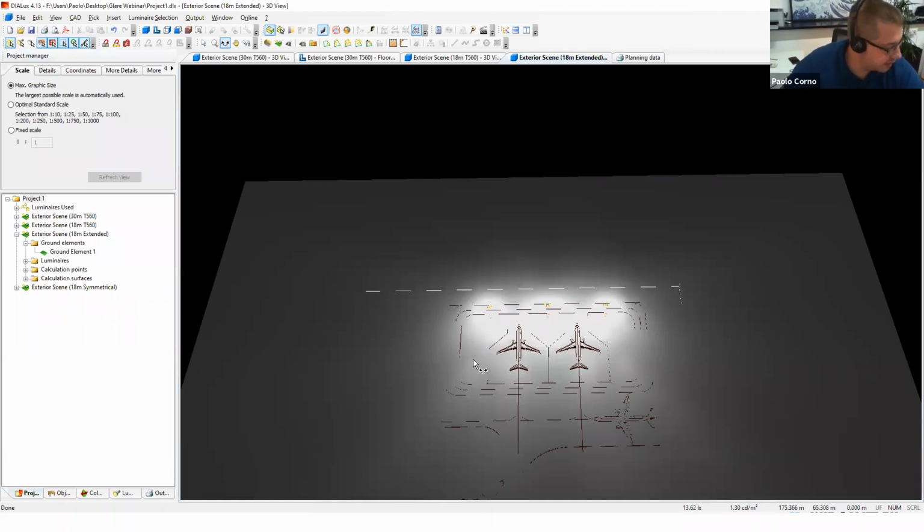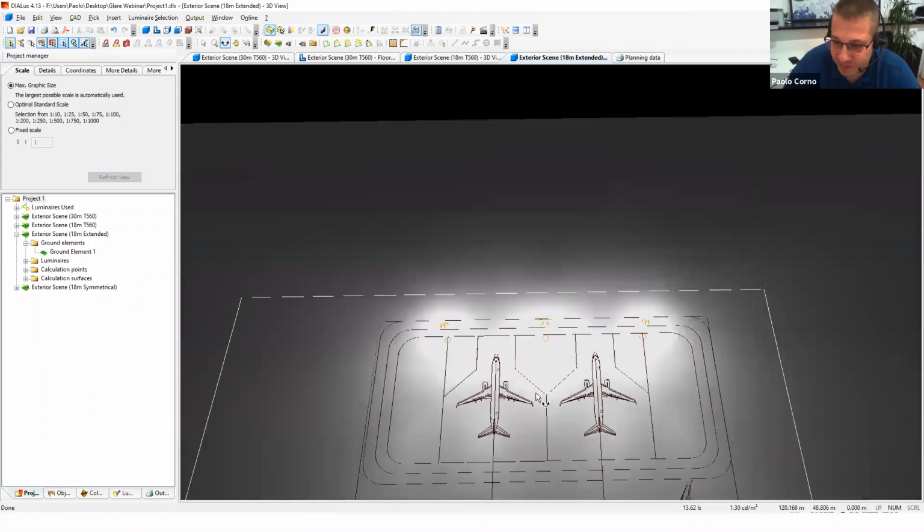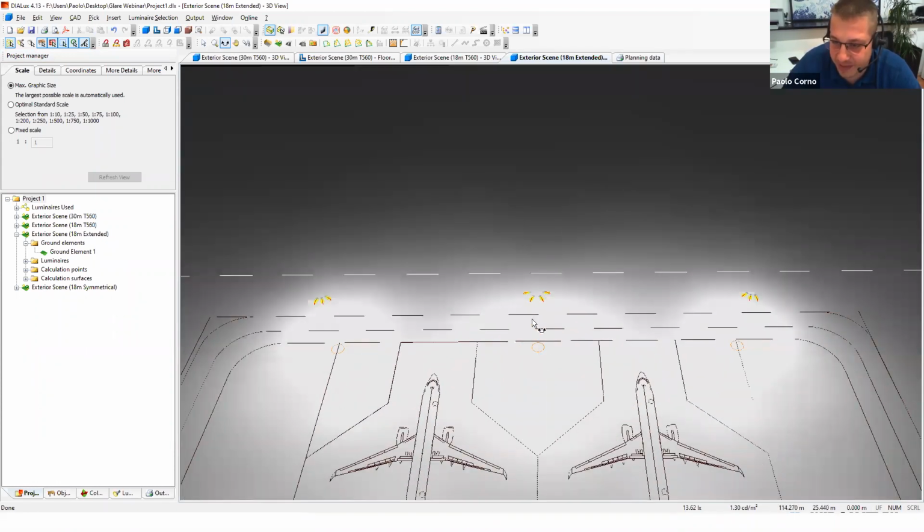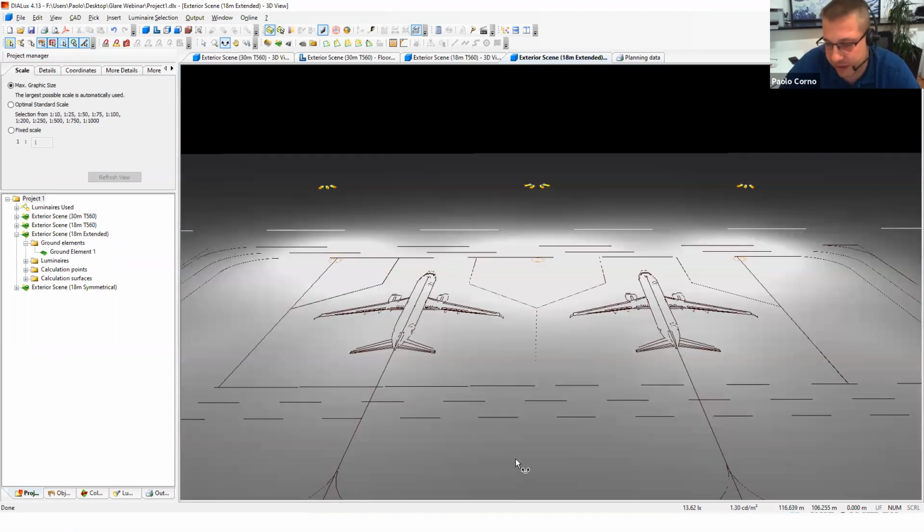But that is actually a very, very smart thing to ask, because it happened in the past in different airports where, for example, you have very concentrating hot spots on the ground, which don't look good, but still they work when the ground is dry. When you actually add the water, the ground becomes a reflector. And so basically you get a direct bounce of the light onto your eyes.